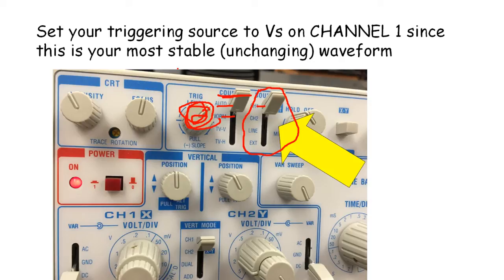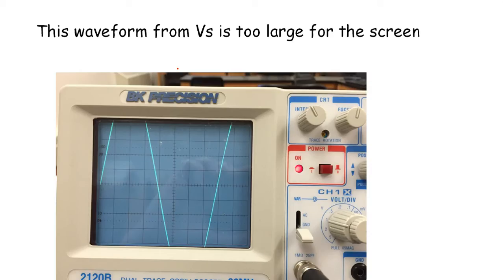If you had your source set to channel 2, you could trigger off of your signal in channel 2. If you had it set to line, that means it's triggering at 60 hertz a second. I don't know why you'd ever want to do that, but it would be if you were looking at something to do with the source in the wall. And then this is if you have some external trigger you want to put into your oscilloscope, but we probably won't ever use that.